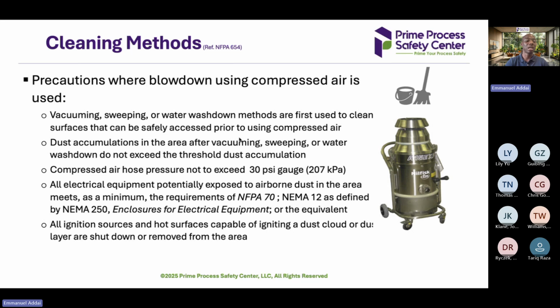Otherwise, it's going to react with the metal to generate hydrogen, which is easier to ignite than even the dust itself. And sometimes, in case you have dust inside the equipment, you try to vacuum and you still have some trace of dust, then you are allowed to use compressed air. But in this case, there is a lot of guidance that you need to follow to ensure that all ignition sources are covered, so that you don't generate a cloud that is going to lodge into a specific ignition source and also cause an explosion.